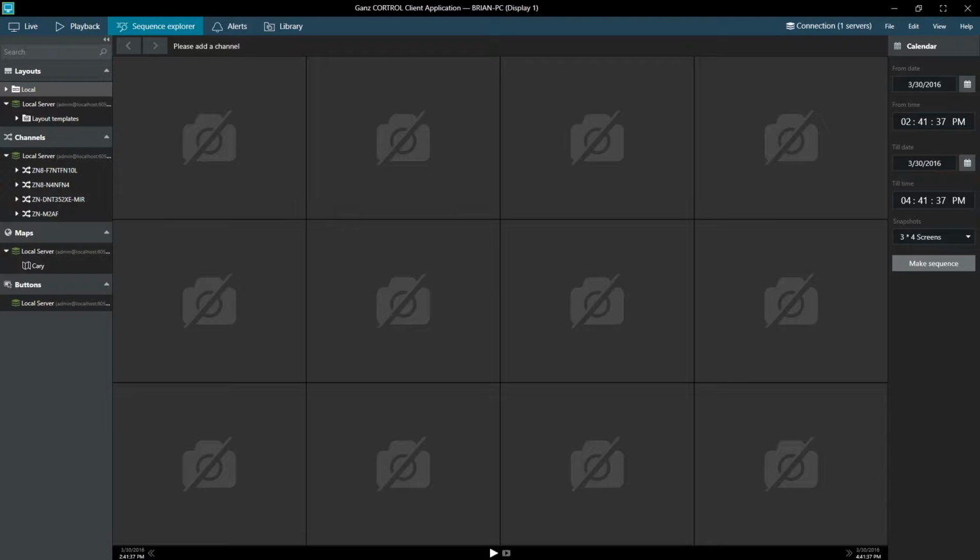A snapshot's layout selection should be determined by the required division of time in an exploration. An example would be a 6-hour time span spread over a 3x4 layout or 12 viewports. At 12 divisions, the time increment per viewport would be 30 minutes. By comparison, the same 6 hours spread over a 5x5 layout or 25 viewports would be 15 minutes per viewport.